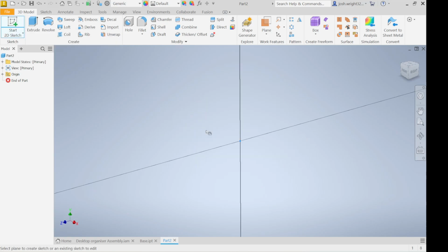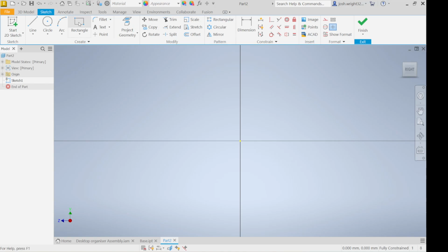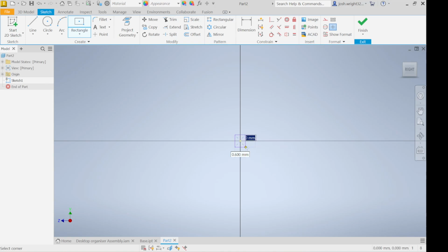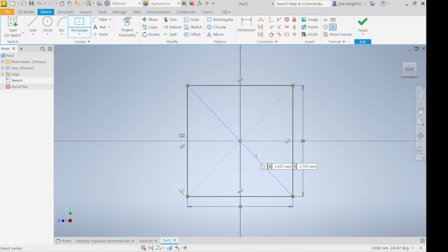Sketch, click on the Y and Z again. Now we just want a 2-point center like we did last time. Click once in the middle, remember, just slowly drag it out. I'm not holding any buttons or anything. So I'm going to go 20 millimeters down, tab, 19 millimeters thick. Alright, so I'm just sticking to that 19 millimeters because that's the thickness of our 140 by 19 part. So then all we need to do is cut a 20 millimeter long piece and it should fit in there nicely.